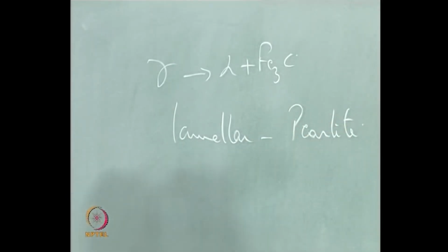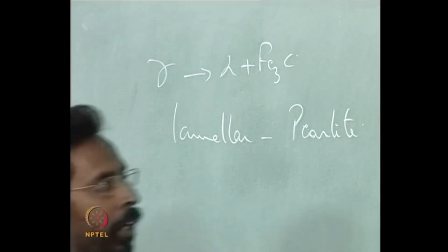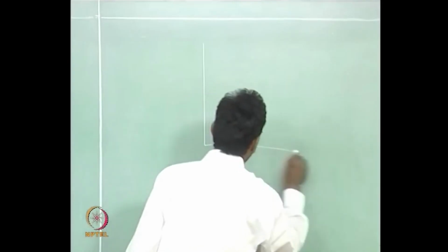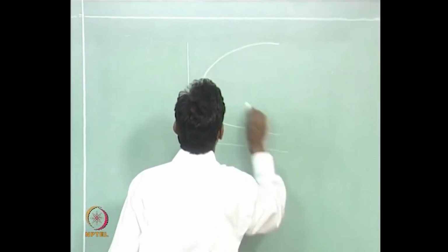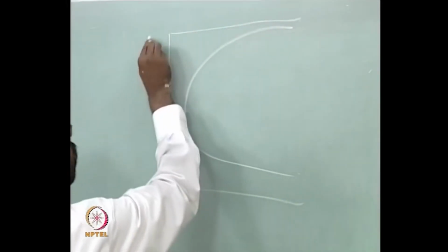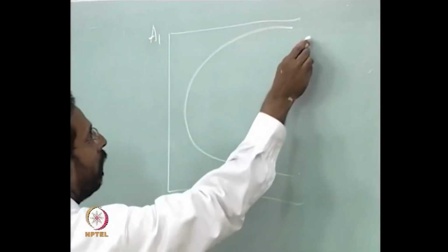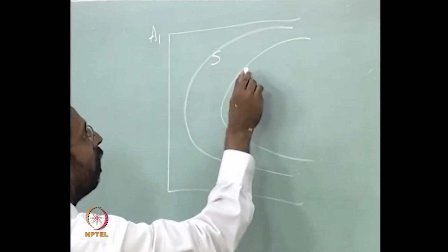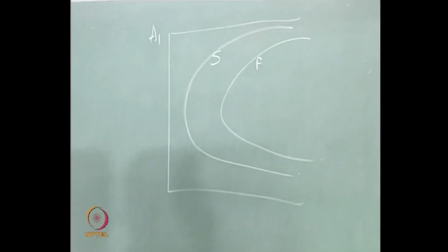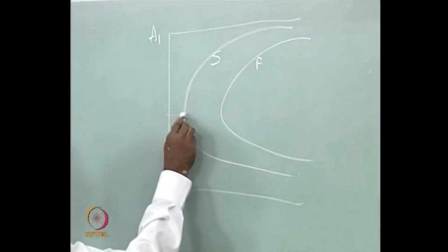and you actually get this usually at higher temperature, at temperatures closer to the A1 temperature, closer to the transformation temperature, when the undercooling is smaller. When the undercooling is larger, you end up in the domain which is, if this is the A1 and this is the start and this is the finish of the pearlite transformation.